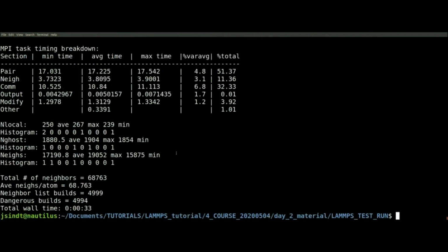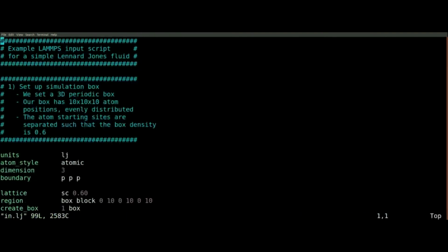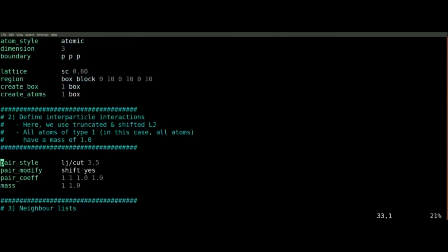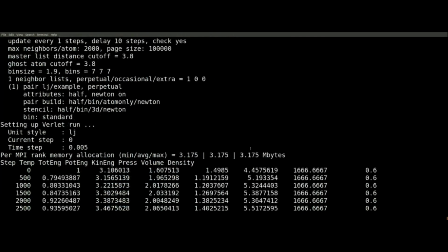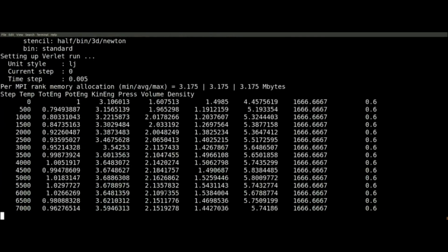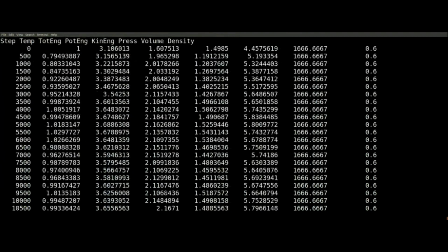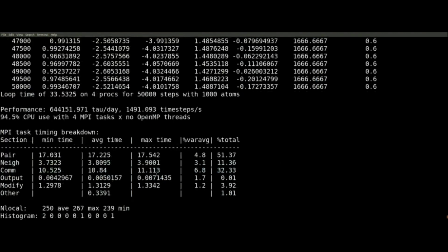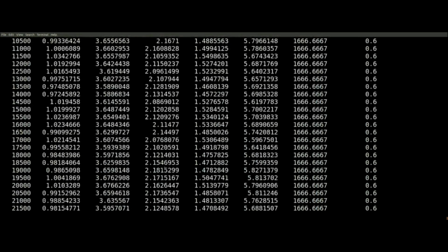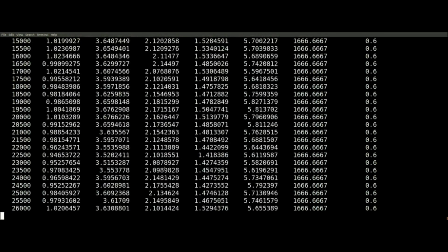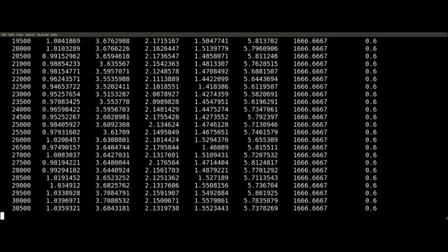That's the idea. So now, let's change our pair style from LJ cut to LJ sample. And if we run that again, there we are. If you look at the fourth column, the entire fourth column is now positive at around +2, whereas in the previous run it was -4. So this is not a proof that we have successfully done this, but it looks like it's outputting the right thing, at least to a first approximation.